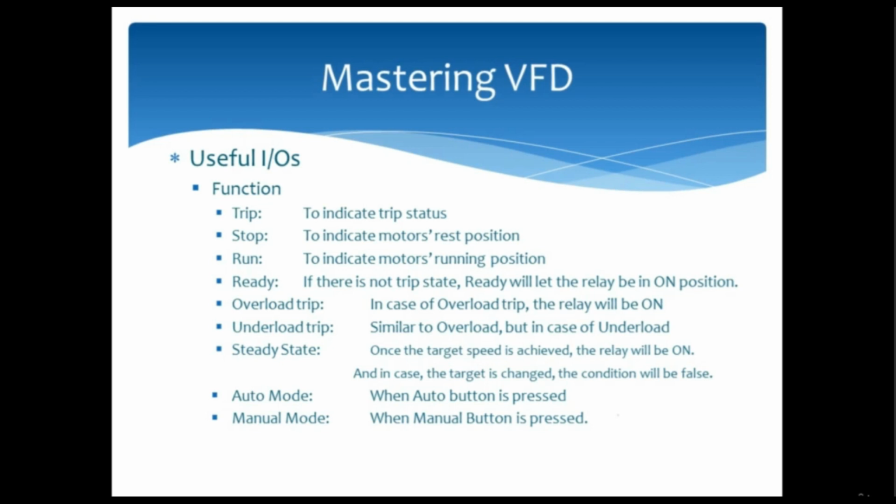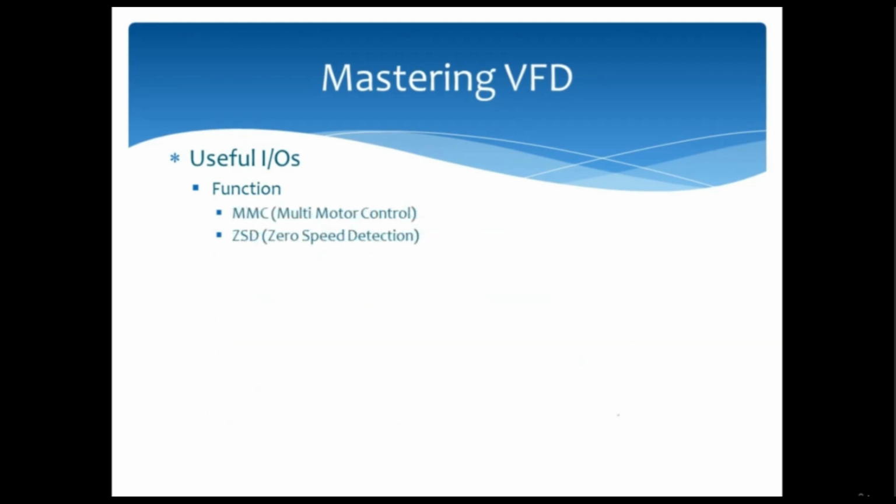In the end, few other important functions. MMC stands for multi-motor control. This function is used in pump application, in which based on pressure feedback we can turn another pump on to support the main pump to meet the pressure requirements. I excluded this topic as this topic requires itself a complete section.